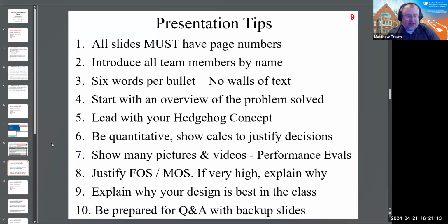Different industries and different product types require different factors of safety, and you should explain upfront why you selected a particular factor of safety. For example, in the aerospace industry, we're expecting a factor of safety of something like 1.1, 1.2, maybe 1.3, because those guys are incredibly concerned with weight, right? So they're basically willing to take on a little bit more risk to reduce weight so that their aircraft or spacecraft function as needed.